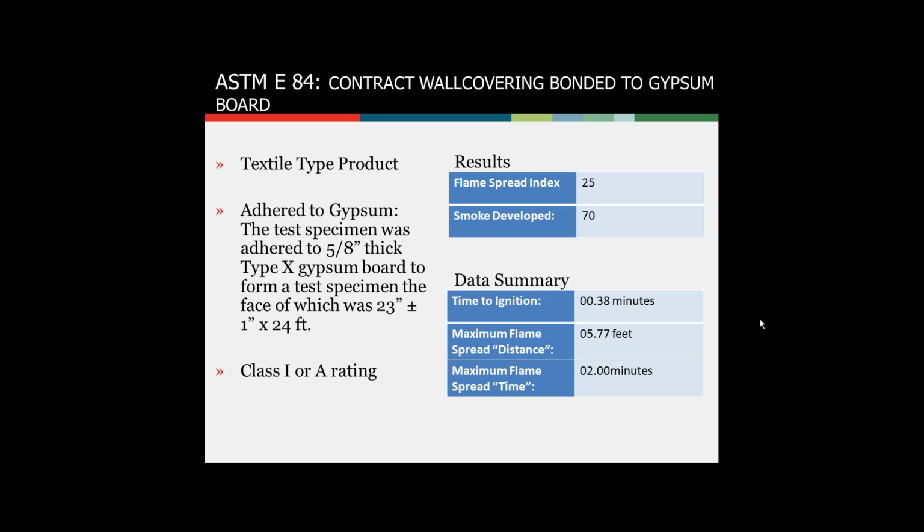And I think, as Mark pointed out, the appropriate test for the hanging material is NFPA 701, yet throughout the land, many fire marshals, all they know is ASTM E84. So you have a conflict between satisfying a fire marshal and doing what the correct test is. Sometimes we recommend both tests, doing the NFPA to protect yourself in the case of product liability, and the ASTM E84 to satisfy the fire marshal.